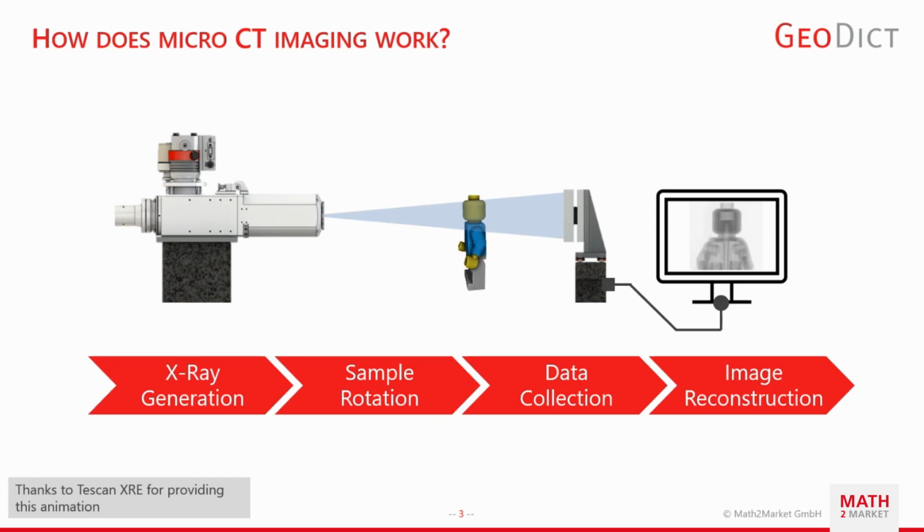So to do the fiber analysis on a CT scan, we first of all need to do a CT scan. So now maybe an introduction, as not everybody here is used to CT scans. How does it work? Well, you have on the left side an X-ray tube that is emitting X-rays, and usually a cone beam for these applications, through a sample that is the turning Lego figure here. And then on the right side, you have a detector that's basically a camera. And with that detector, you take images of the sample rotating, so-called projections. It's what you're seeing on the right on the screen.